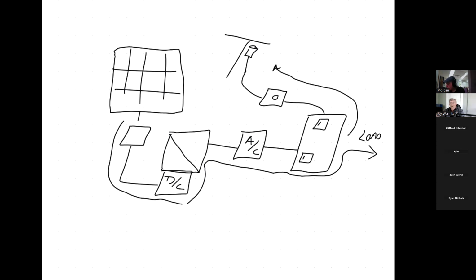They also can ride out those momentary flickers. You know, they will operate under less restrictive voltage requirements. So if the grid drops a little bit, you see sometimes your lights dim and then come back up. You know, that's just kind of a temporary, a transient voltage drop out there on the grid. Your inverter's designed to ride through that. So there's a lot of those kind of transient ride through things. And they'll also clean up the power, and they're doing all of this other stuff.